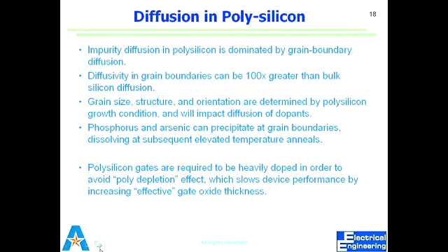So they would be boundaries of many boundaries, if you look at polysilicon. Each grain has a localized crystalline structure, right? So these boundaries now give many more locations for dopant incorporation, right? That's 100 times greater than bulk silicon diffusion, which makes it heavily doped.